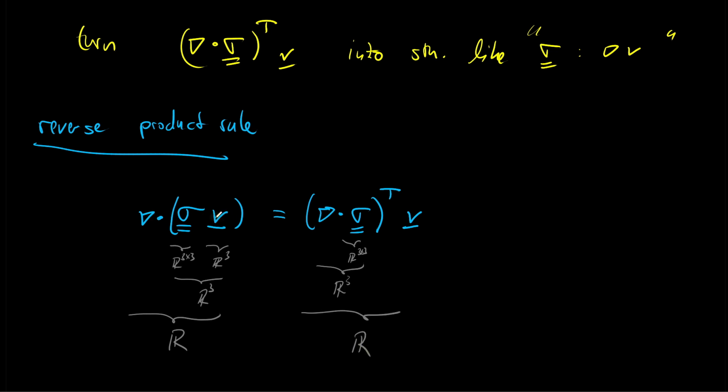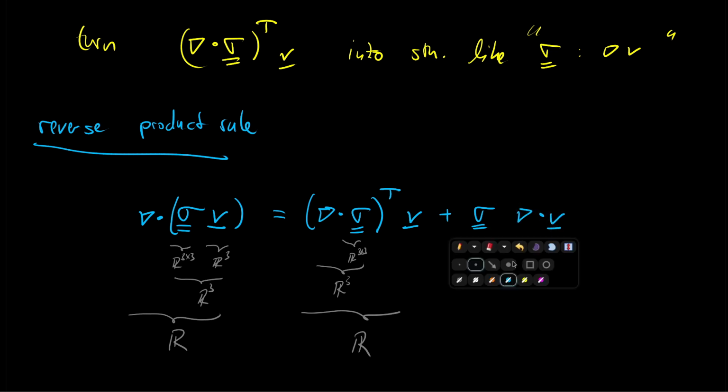But now we have to also apply the divergence to the V test function. So we will get the sigma matrix multiplied with the divergence of V. Okay, well, let's play around. So this one was a 3D vector. And if we take the divergence of it, we will get a scalar. And then here we have our 3x3 matrix. That does not work. So the 3x3 matrix multiplied with a scalar will give us a 3x3 matrix. So the equation would not be fulfilled.